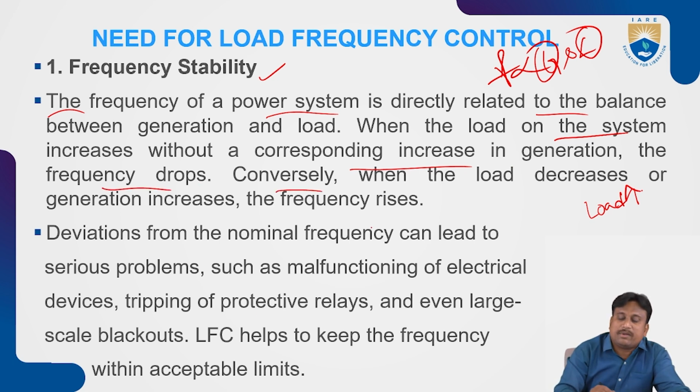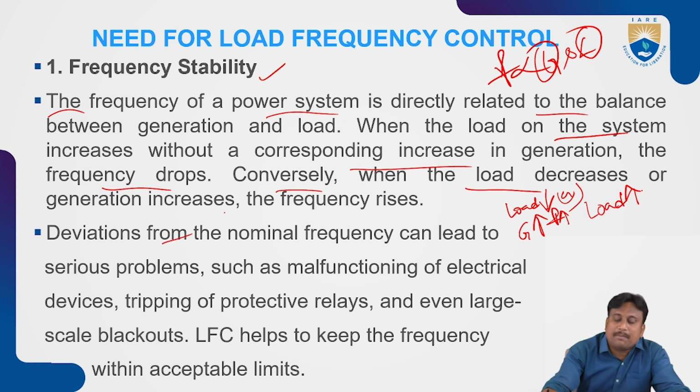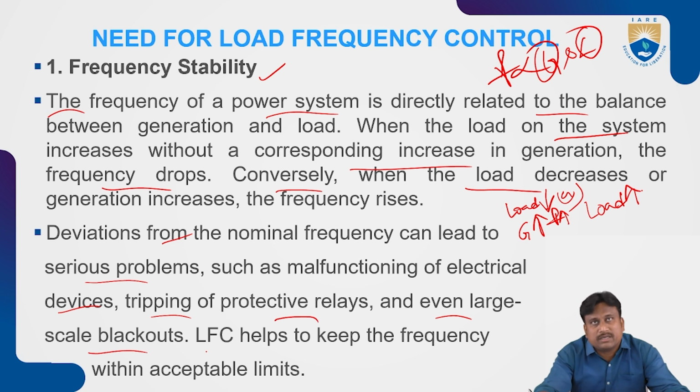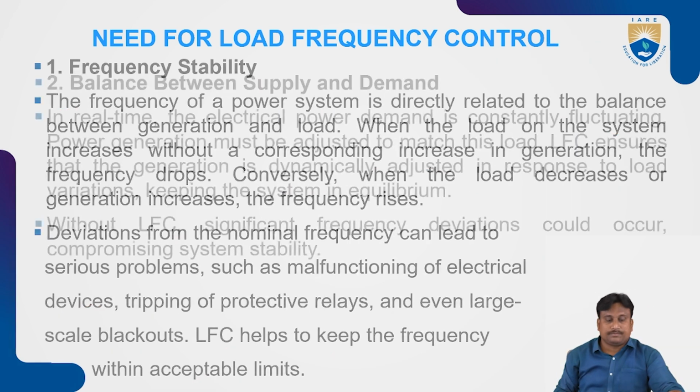Conversely, when the load decreases or generation increases, the frequency may rise. That means frequency is going to increase back. Here the deviations from the nominal frequency may lead to serious problems, such as malfunctioning of electrical devices, tripping of protective relays, and even large scale blackouts are to be expected. So load frequency control helps to keep the frequency within the acceptable limits.